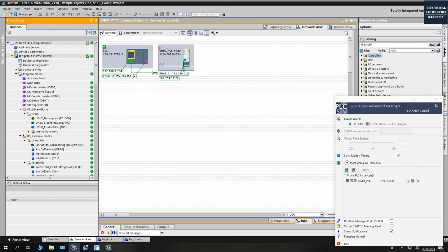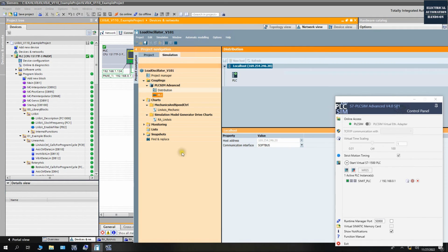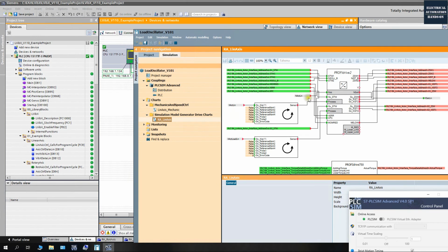And here, I'd like to mention one thing. From this network view, we will see this SINAMICS S120 drive is showing disconnected. It actually doesn't matter. That's because of the simulation software. As long as all those interfaces that represent the telegrams, the inputs and outputs, IW, ID, right?